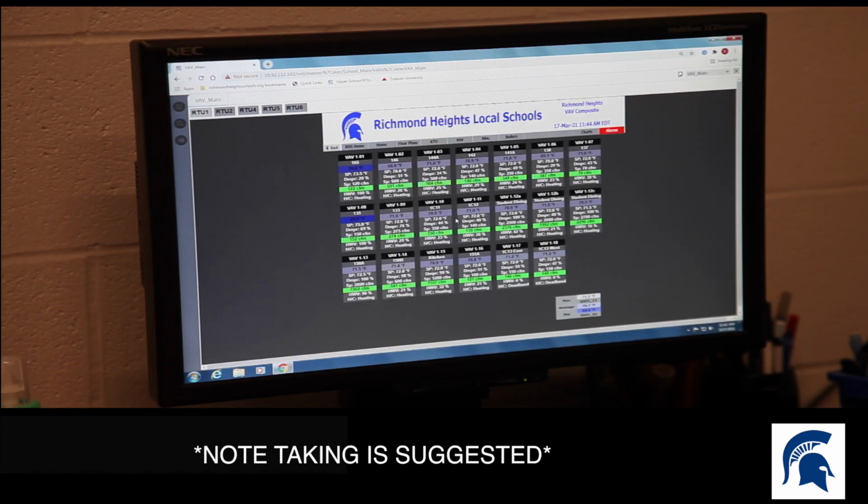And one thing we have that can potentially stagger the starts, and we have it in this system as well, is an optimized start and stop logic block that we can put in here. You feed the schedule in, and then you feed in the outside air, and then we use the average room temperature for area units, or just the room temperature for single zone units.